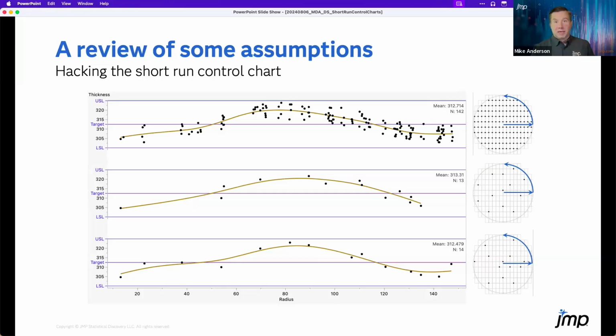the other two problems that we have, the sampling plan, the lack of randomization, and that assignable cause are leading us, if we look very closely here, if we were to take the mean, and let's set aside for the second whether or not this is the right thing to do, we're just going to use this for illustration purposes. The mean of this data is around 112, call it 113 with the rounding error. This sampling plan gives us almost a full unit high, or almost a full half unit high, let's call it. But a different sampling plan can get us to where it's within rounding error of being the actual number that we would expect.